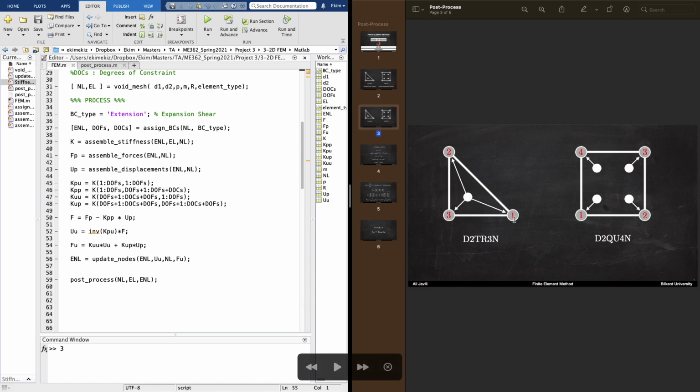Why? Because we have the different displacements of different nodes at hand already in our extended node list. So naturally, since we have 4 different values for the different nodes for the stresses and strains, in the 4-noded element, these values will vary along the element.